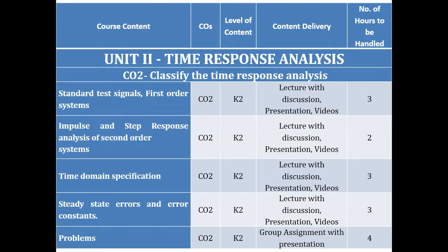By a simple equation we can't express the input signal, so we will use some test signals for the analysis of the control system. So we will go for this time response analysis. For this we will consider different types of signals, and we will analyze the response of the system: what's the peak time, what's the rise time, how much delay we have, how much overshoot we have. All those things we will learn in this time response analysis.